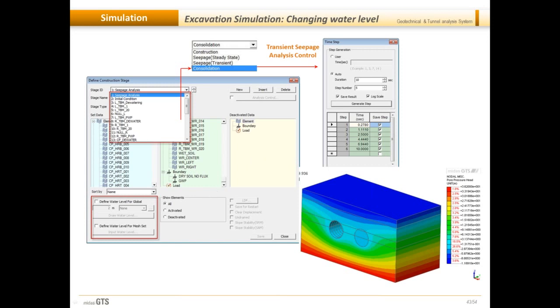But in clay soil, what happens is after the tunnel has been constructed and the lining is installed, the ground displacements are likely to be seen to continue at the surface. So you will see the surface still deforming even after you have finished the construction and you have installed the linings and all.